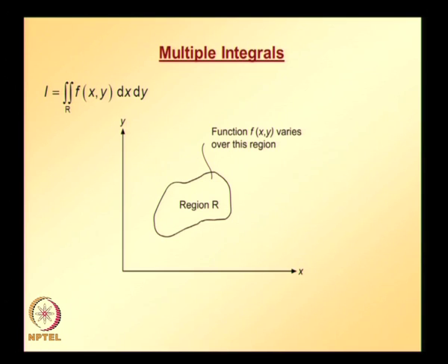So now basically what we require to do, we need to find this integral. We require to decide how many integration points we want to use along x direction and y direction. So this integral f(x,y) dx dy is approximated as the function f(x,y) evaluated at a certain number of points along x direction, y direction.